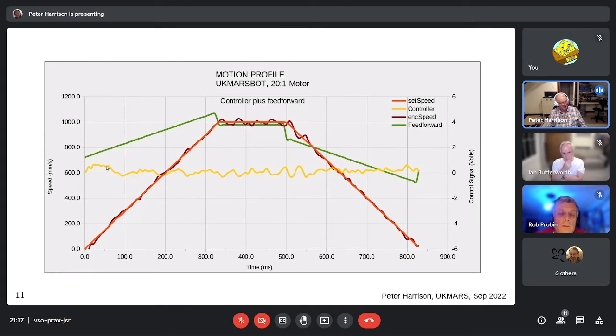And in fact, that would be parallel to that line there. But it doesn't. There's a step. There's a small step just because of that bias. But remember, the bias was only 200 millivolts. But this step is the additional voltage needed to drive accelerating current into the motor.